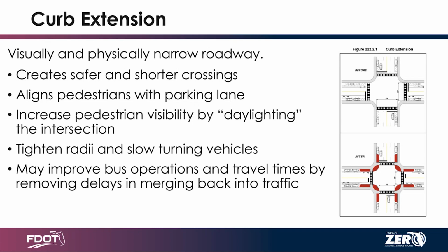Yep, and we're not going to get into the details, but at signalized intersections, you could also introduce things like two-stage crossings, so a pedestrian goes halfway with another left turn phase. There are efficiencies you can build in with curb and median extensions that reduce pedestrian delays and potentially reduce vehicle delays as well. So we could be seeing operational and safety benefits.